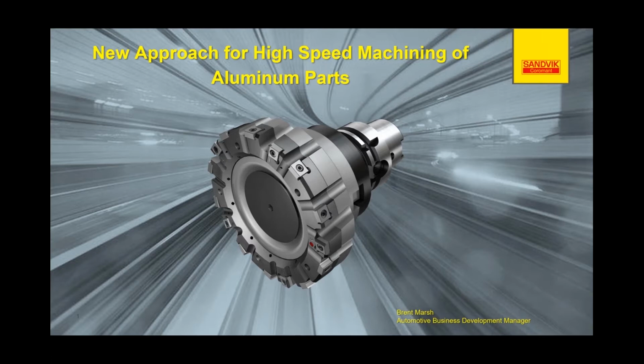We know that aluminum is a relatively easy material to cut, but it does have some challenges. Typically those challenges are surface finish requirements, flatness requirements, and clinging burrs, because the material is very ductile. So it's often a problem to get rid of burrs. Typically you can mill an aluminum surface faster than you can deburr it.